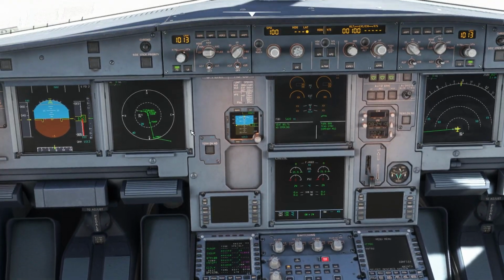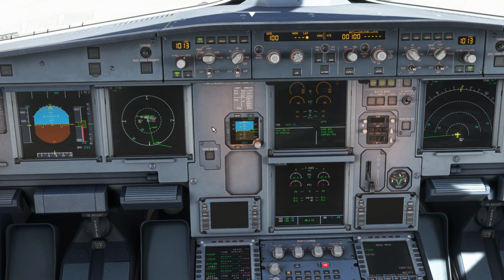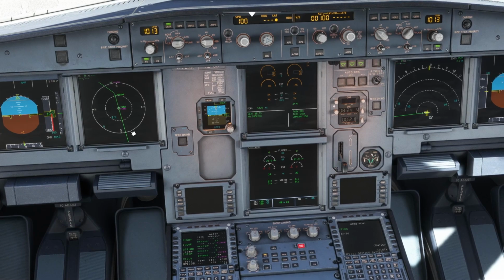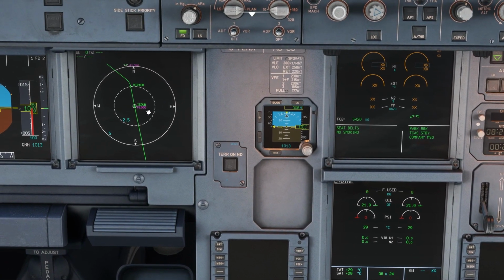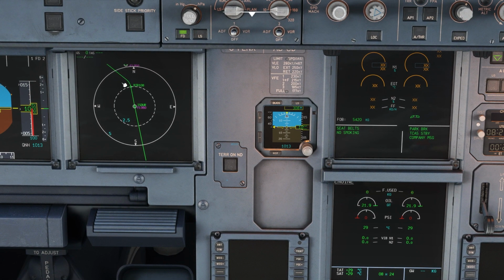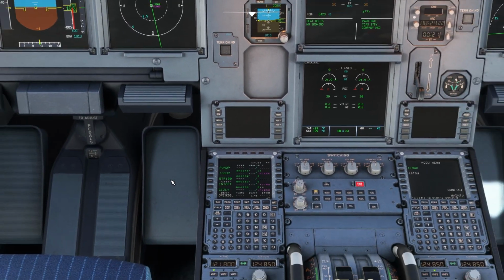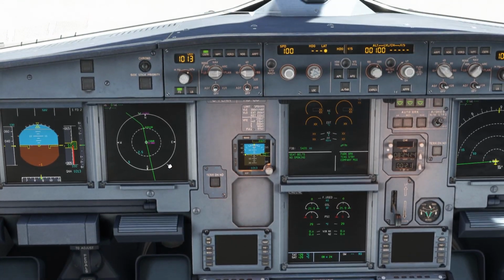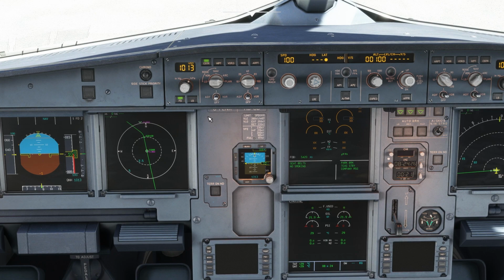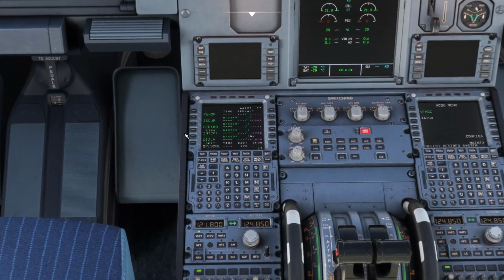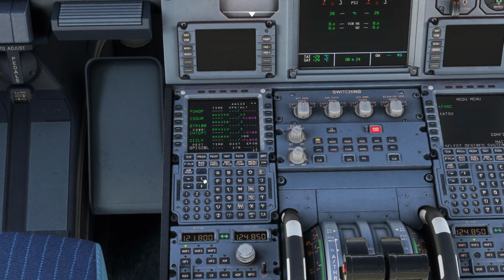Okay, and if I turn on constraints, will I be able to see the constraints? Yes. So it's a very good thing to even look at the constraints during the flight, that at this altitude you should be at 6,000 feet, and over here at this waypoint you should be plus 5,000. So if any constraint is there, it will also appear over here in the navigation display. So you have to turn this option on, constraint. Let's move it back to arc, and you can see all the constraints are also coming over here in the flight plan. So that's it. So secondary flight plan done.